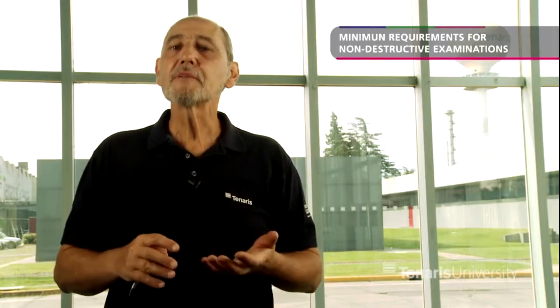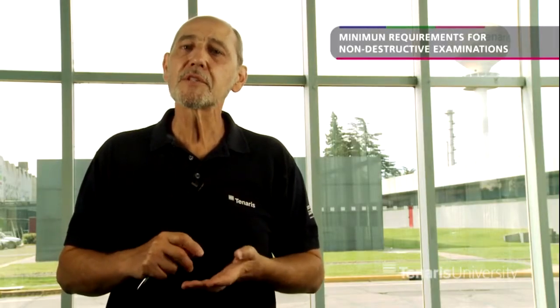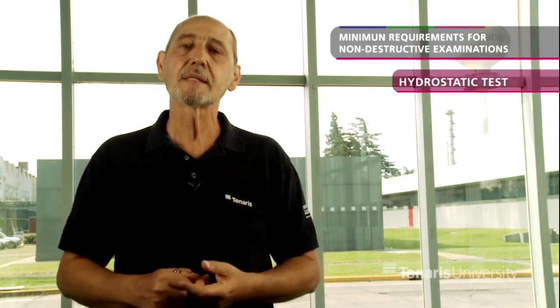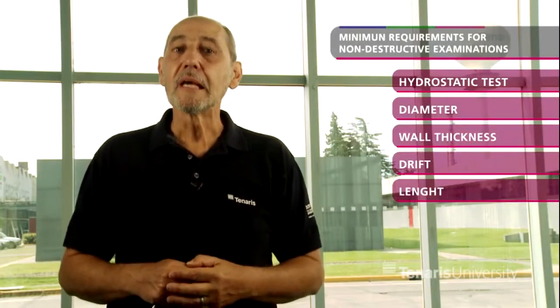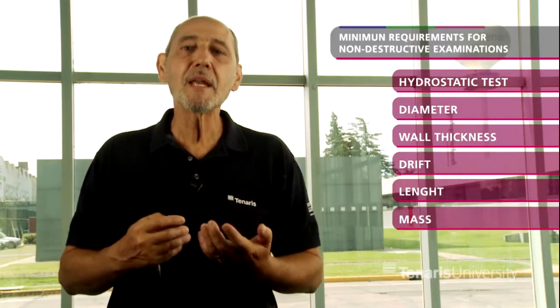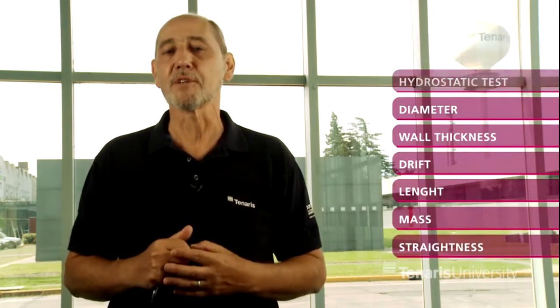Minimum requirements for non-destructive examinations include hydrostatic test, dimensional control like diameter, wall thickness, drift, and length, as well as mass determination and straightness evaluation.